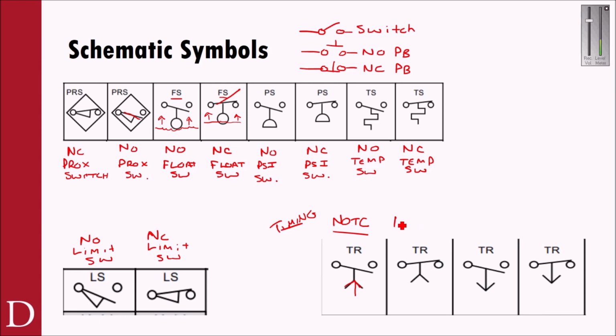This one is normally closed. Okay, I can see it is shown in a closed position, and it's important to pay attention to that action too, right? It's going to be pressed up, so it's normally closed, timed to open. This one here is normally open, timed to open. So it's drawn as normally open, but look at the direction that this is going. It's going in the opening direction.